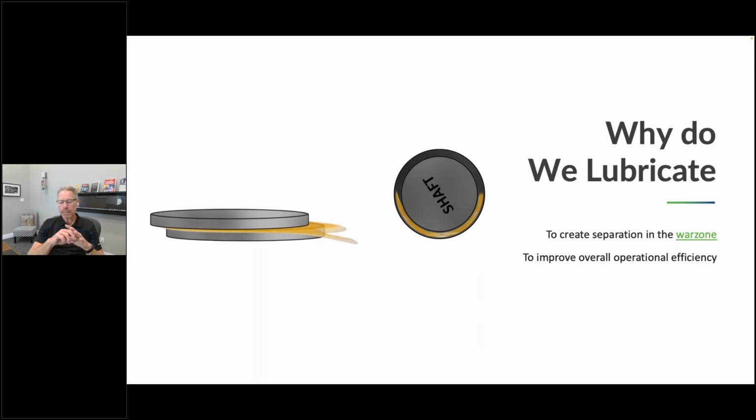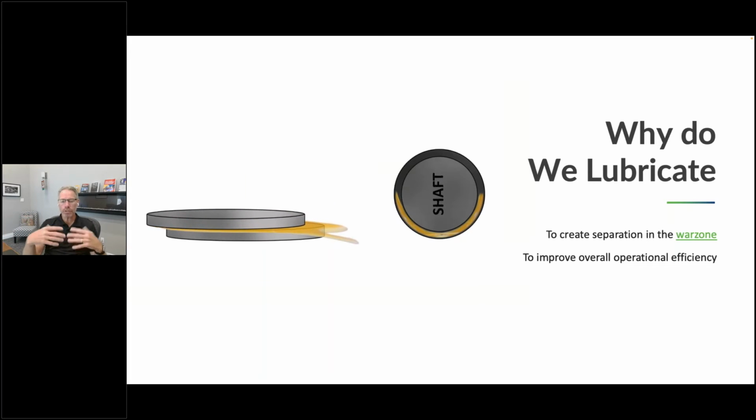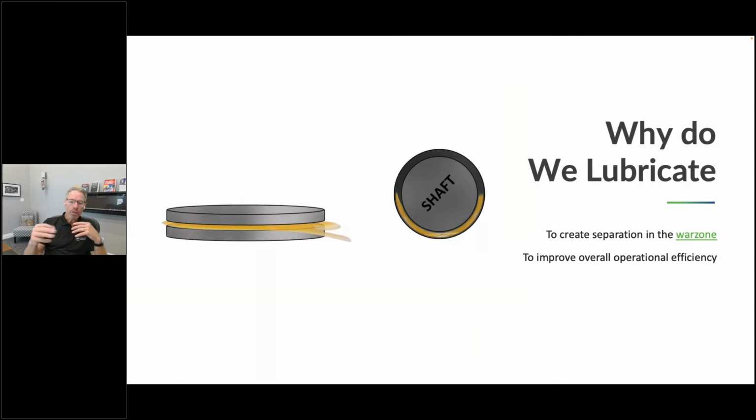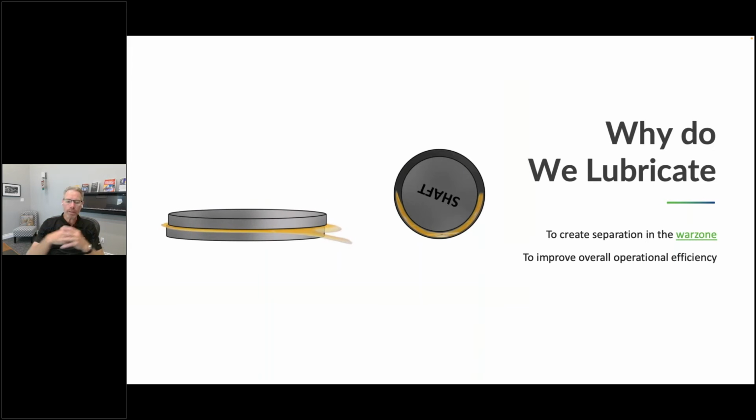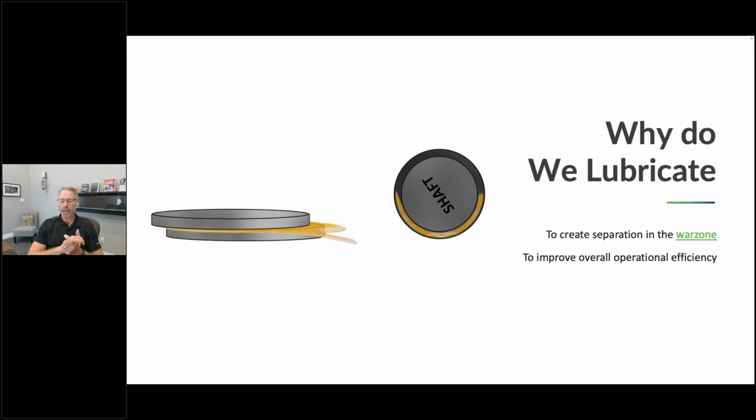If that's clear, then when we lubricate bearings, and more specifically, when we grease bearings right, we achieve low friction, low temperature, and bearings have the best possible chance to exceed their engineered lifespan. So our goal has to be to achieve that perfect film and then maintain it. But it doesn't last forever. That perfect lubricating oil film is going to break down.